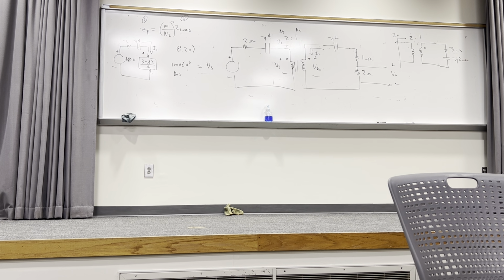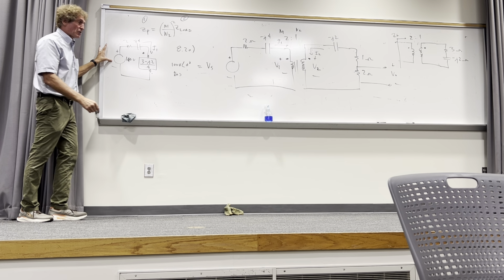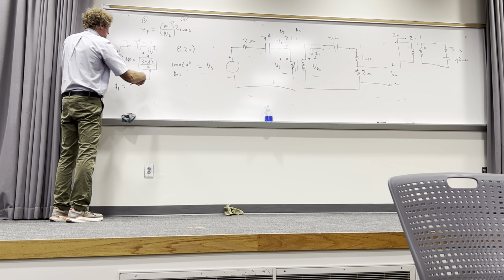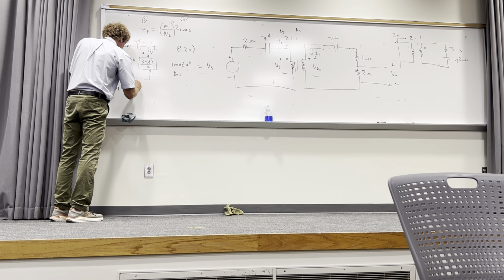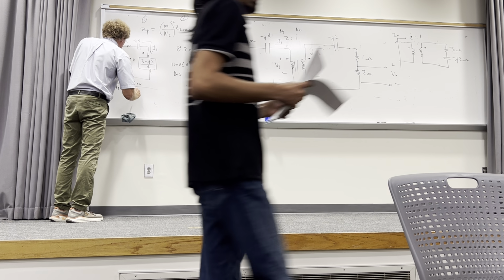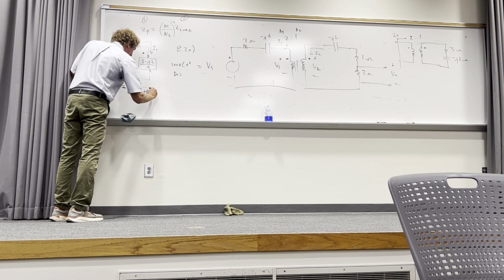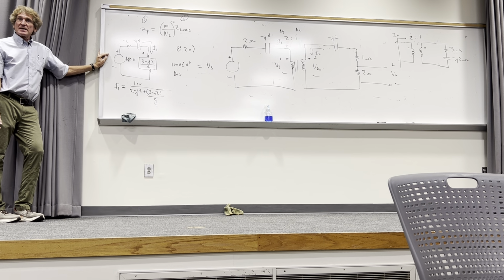Now that current is found just like you find any other current. You take the total series impedance and divide it into the source voltage. So I1 would be equal to 100 volts, or Vs, divided by 2 minus J4 plus quantity 3 minus J2 over 4. I'm leaving it that way so you can see where I got everything. Can everybody see that and understand that?